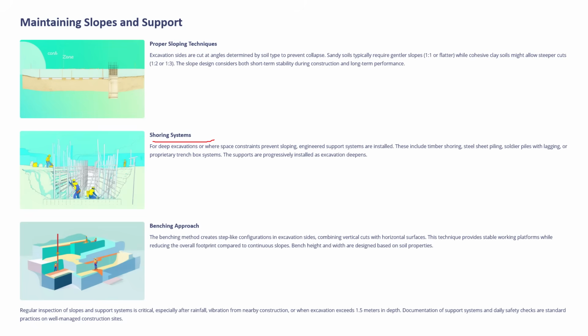Instead of shoring systems, you may use a benching approach. So what is the benching approach? In the benching approach, we create a step-like configuration in excavation sites, combining vertical cuts with horizontal surfaces. The technique provides stable working platforms while reducing the overall footprint compared to a continuous slope. Bench height and width are designed based upon the soil properties.